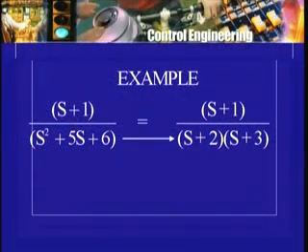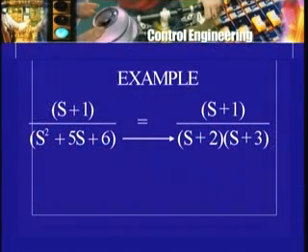As an example, such a rational function may be: the numerator is s plus 1 and the denominator is s squared plus 5s plus 6. And if I ask you, well, what differential equation could it be for which you obtain this transfer function? The inverse question: given the differential equation, find out the transfer function. With little practice, you will be able to do it without any delay. Simply replace d by s, appropriately, and you will get the transfer function.